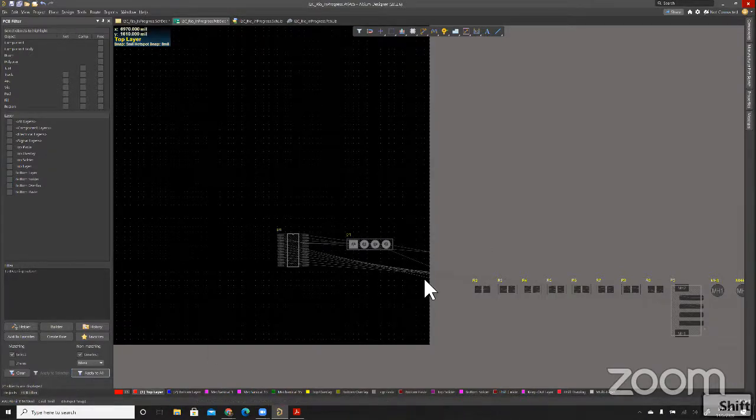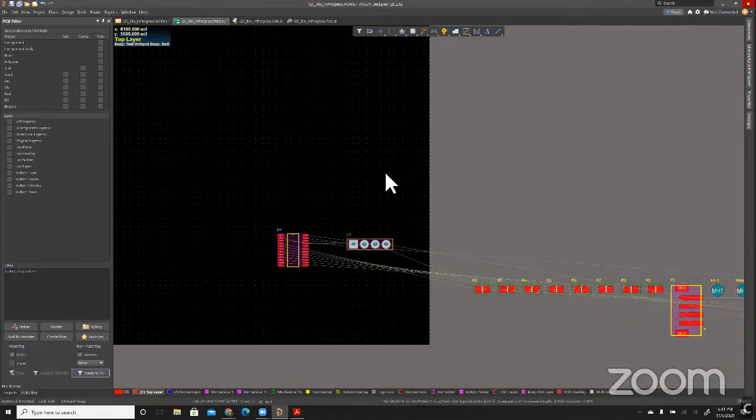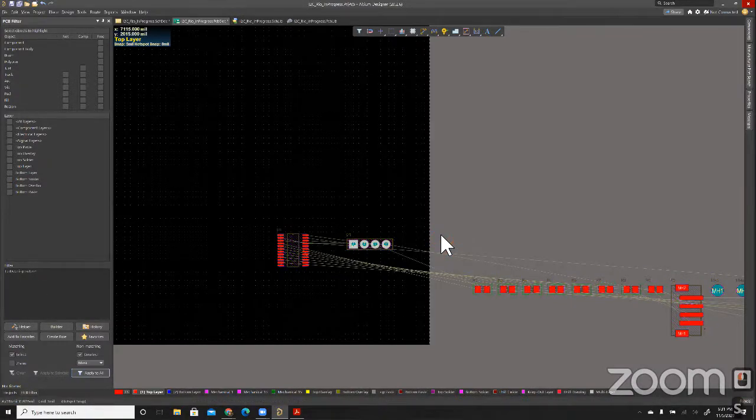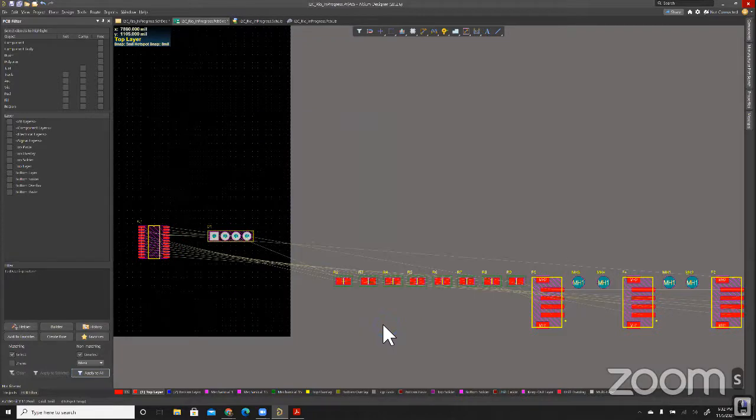And so you'd have to hit Shift C to clear it. So right there, it was masking out anything that wasn't the designator because that's what I wanted to modify. Shift S will change it so that now I'm just looking at things that are on the top layer. And if I hit Shift S again, it really hides everything that's not on the top layer. And then Shift S again now brings up everything so I can see all the different layers. And I'll show some more examples of that later.